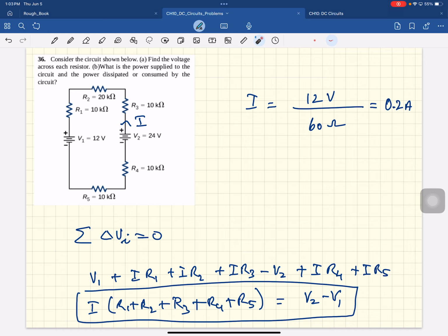Question. When you're doing your Kirchhoff voltage law, what's your logic for determining the signs of each thing? When you're flowing against the current, you're going uphill, so that's positive. And when you're going across a battery, when you go from low to high, that's positive. When you go from high to low, that's negative. That's the opposite of what it seems it should be. I'm just used to a different convention, but that makes sense.